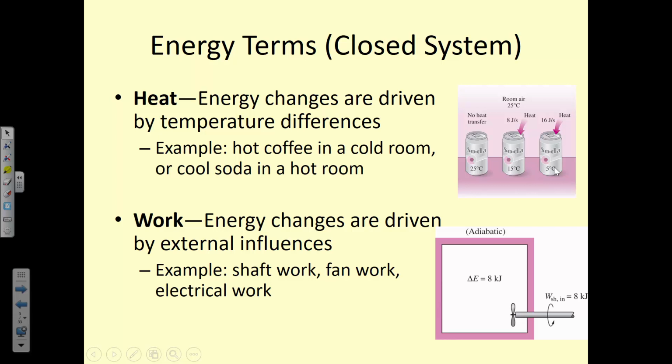And work crosses the boundary not necessarily in a physical manner. Sometimes boundary work is represented by a boundary moving. But a shaft that crosses the boundary of the system is considered work crossing the boundary, even though the propeller itself is inside the system. Similarly, if there's any kind of electrical connection to our system, that would be considered work crossing the boundary of the system.